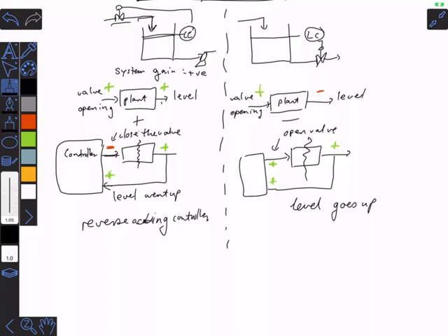So the question is really at that moment, starting at zero, if the controlled variable at that moment is positive, what should the controller do at that moment to make everything better again? We're not saying what will eventually happen, because eventually the signs will be flipping all over the show. As with integral or whatever, there may be moments where the controller is opening the valve and the level is going up; the controller doesn't always do perfect control.